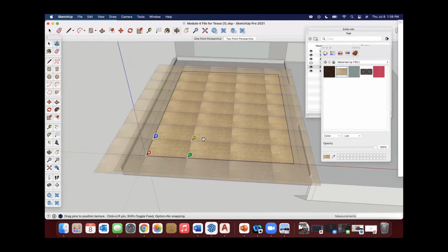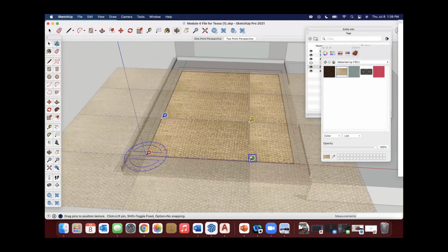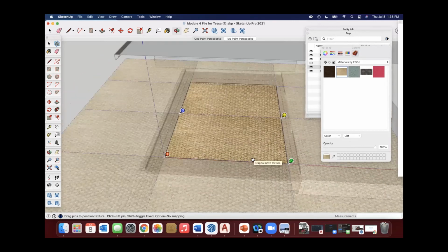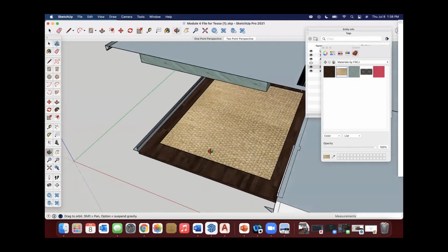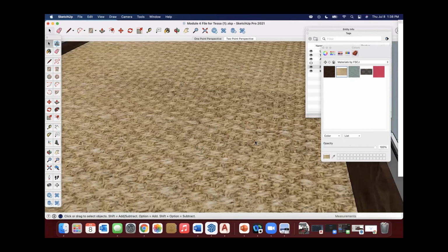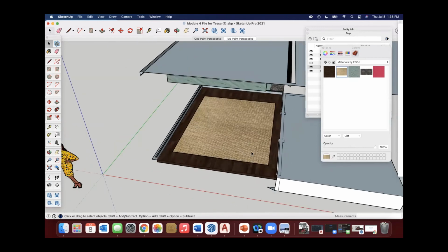I can see that the tiling is a little off. So I'm going to try to scale this up a little bit, and you could always rotate. Now this is going to show really big. I'm going to press enter to show you, obviously that's a jute and the texture is showing really large, but now we're not getting all that tiling. This image itself is a little hard to work with, because there's a gradient in the actual pattern itself.